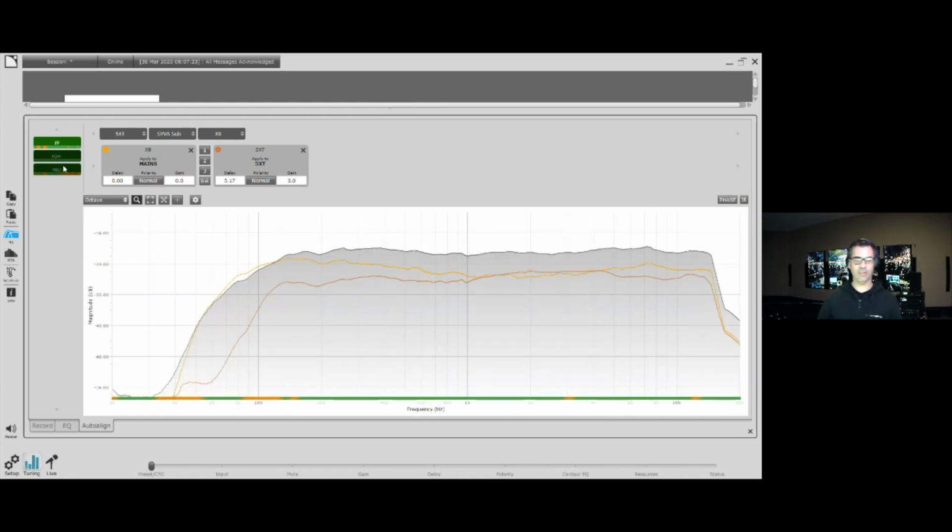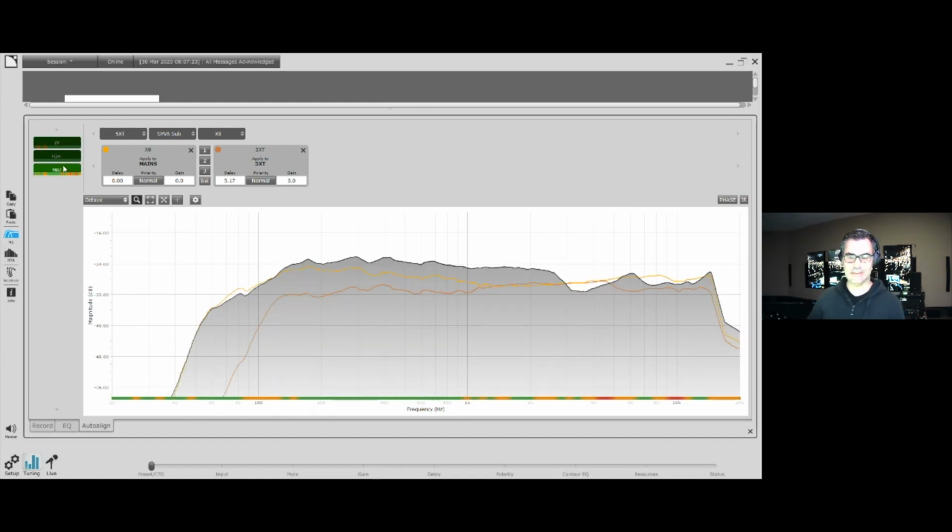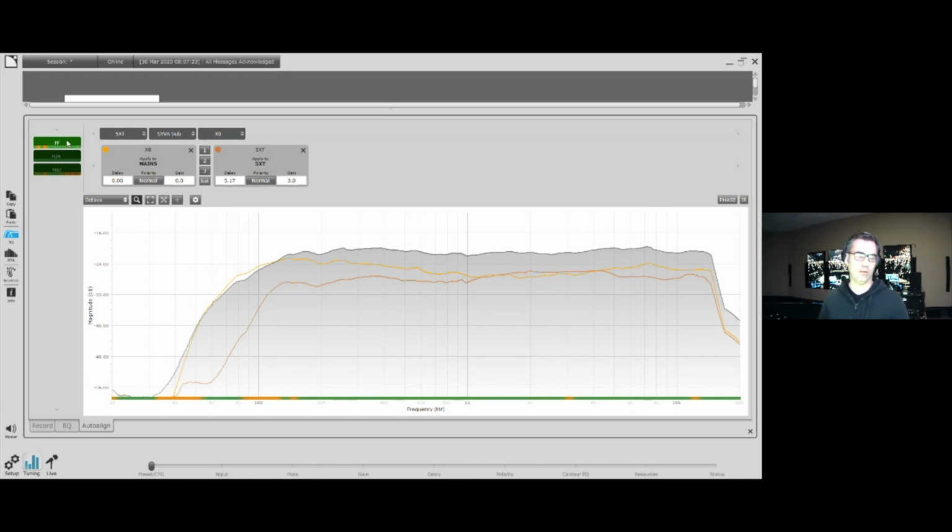We can see at the mid position, it's a bit more challenged, and that makes sense because it was further back in the venue. We're going to have a different time of flight. In this case, our venue was very small, and our two microphone locations were only a meter apart, so it's not a huge difference. But with front fills, we often only get the choice to align it as best we can in one particular location. So all of that can be done within AutoAlign.